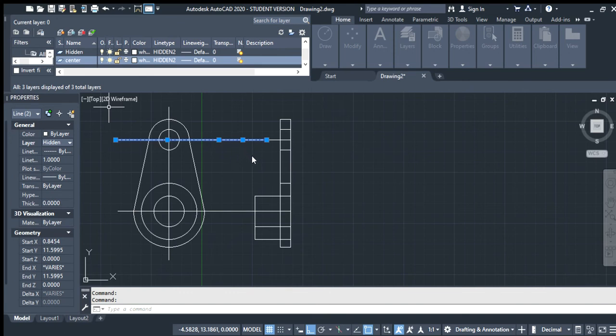No, I selected border accidentally. Go down to center, and when you find center 2, there we go. Go ahead and hit OK. Okay, cancel. And then you go to center 2, hit OK. You've now selected that. So now we'll go back to our lines and we'll hit center. And you'll see it now looks just like the drawing has. Okay, we'll do that to all the lines that are supposed to be dashed.